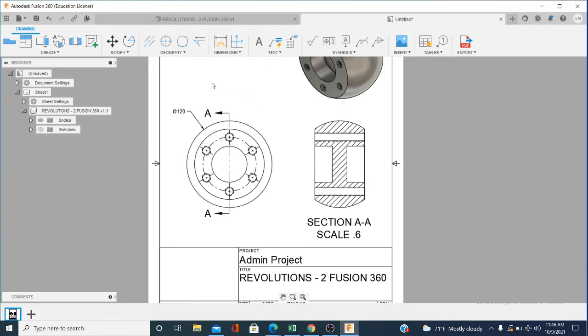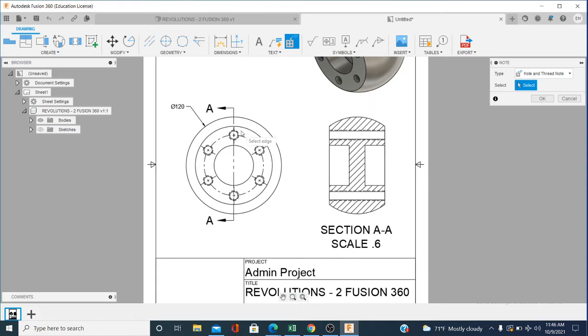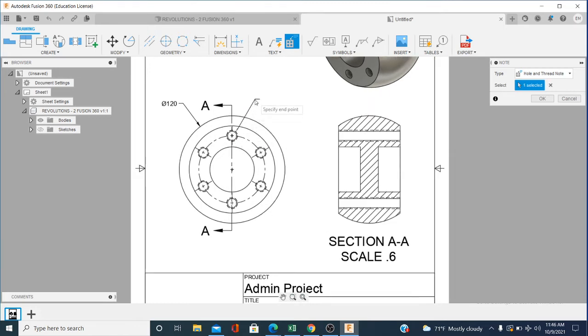Right click, OK. And then I'm going to use this icon here. I think this is neat: click on the hole and come up and click again. And it's going to give us the nomenclature associated with that hole. Look, it's a metric thread, 12 millimeters in diameter, and the pitch, the distance from one thread to the next, is 1.75 millimeters. This is the classification of fit. And then the 70 is how deep. And this is like the minor diameter here.